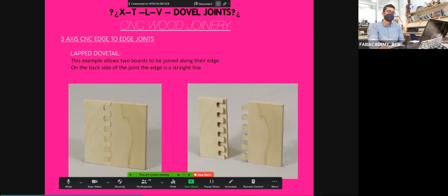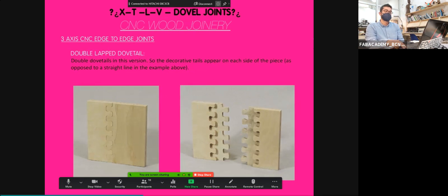We have soft shapes that are based on the round thing. You don't need to do dog bones because the end mill already gets it, and actually you can see it here. This joinery is like that to avoid it. That is called the dovetail. Instead of making a connection like square, you make it round, and you don't need to do dog bones.